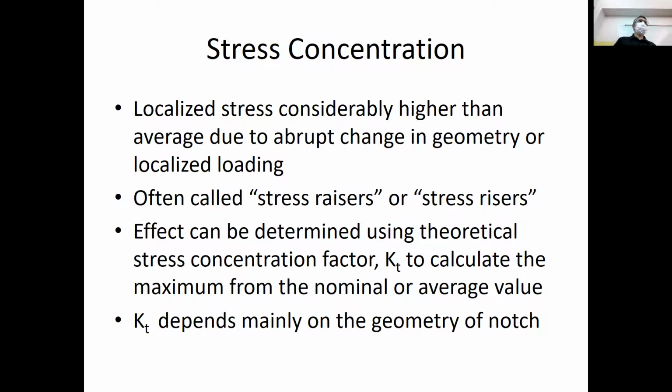Another topic that you started learning about in solids and used in intro to machine design is stress concentration. This stress concentration occurs primarily due to geometric changes. Geometric changes call for higher stresses that sometimes are referred to as stress raisers or stress risers.